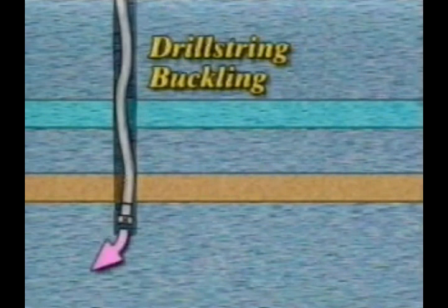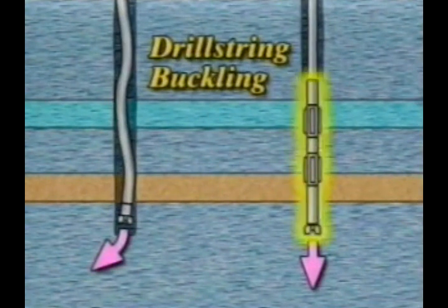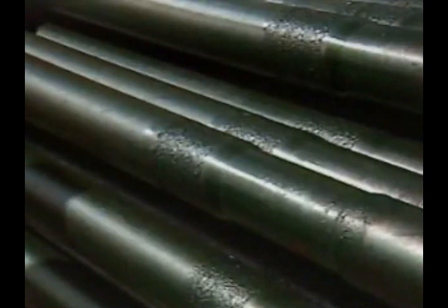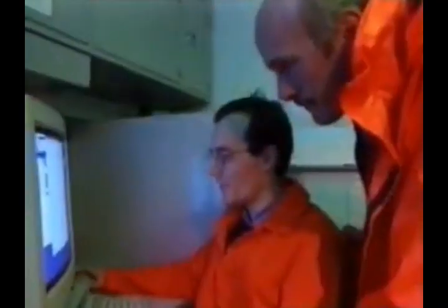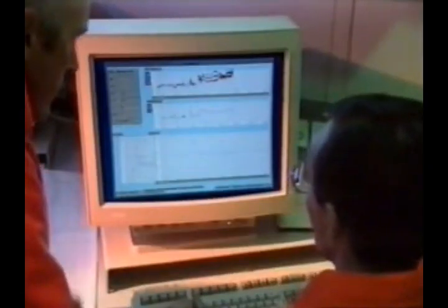The extent to which deviation occurs is based on the drill string's buckling tendencies, which in effect dictate bit trajectory. For a given depth, hole geometry, and weight on bit, the degree of drill string buckling depends on the stiffness of the bottom hole assembly. By using stabilizers and large diameter drill collars at locations of maximum deflection in the predicted buckling mode, we can control the bit's lateral movement. The use of steerable or navigation drilling systems, which allow the driller to monitor and control bit trajectory from the surface, can largely negate natural hole deviation tendencies.